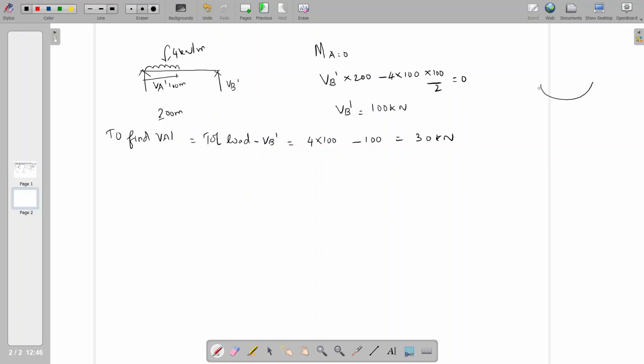So in our cable with the stiffened girder, we obtained VA dash and VB dash, and we need H1, the reaction H1 at the girder level due to the live load only. You have to remember that the girder is analyzed only with the live load because the dead load represents the cable's self weight, so it is accounted for in the cable analysis only.